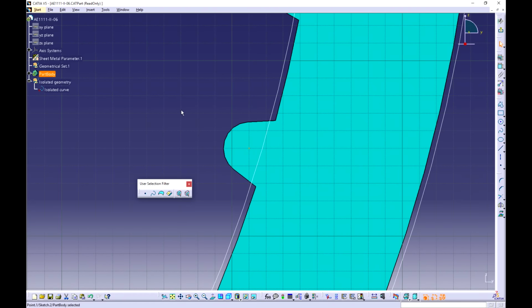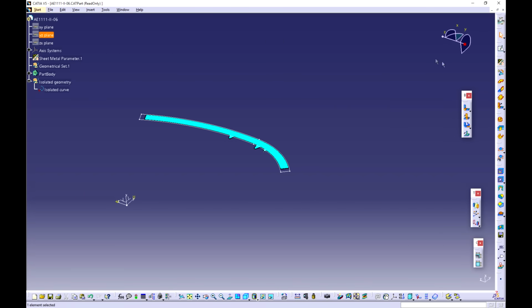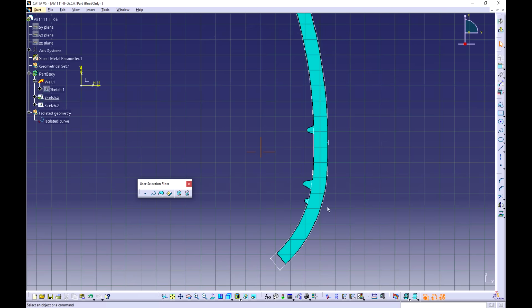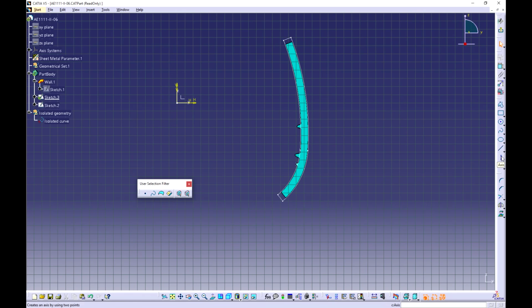This is the point. Okay, then we can leave the sketch and click again on YZ plane and make another sketch. This is sketch 3. Okay, now we are making an axis. On the right side you find the two axes and just place it below the x-axis like this. Never mind how big it is. And then we select the point, double click it so you don't have to click it again, and place the first point at the top of your axis. So it's coincident with the last point.